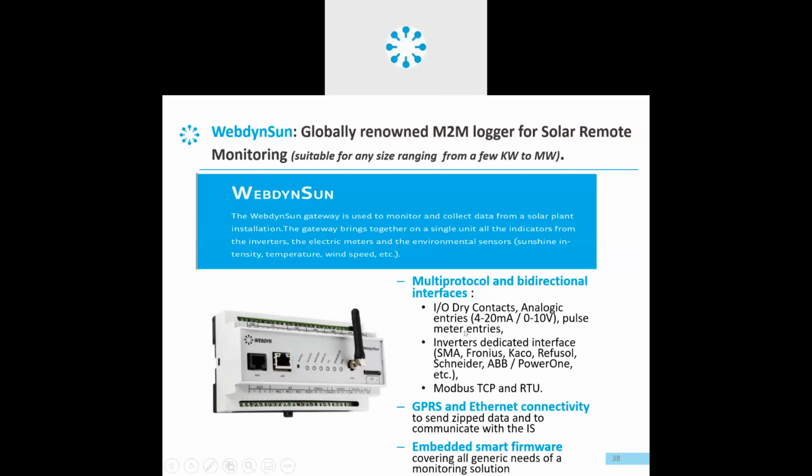And the relay contacts. SPDs are always good to utilize, because an SPD works as an additional safety device when you are connecting your Modbus devices, for example, in a chain. Because any Modbus device, if it is not connected properly or has a fault, can create a surge, and this surge can damage the port of the data logger itself, and in reverse, it may damage the sensor or the string monitoring boxes if you have connected them. So it's always better to use SPDs, communication SPDs specifically, even if not the power SPD.